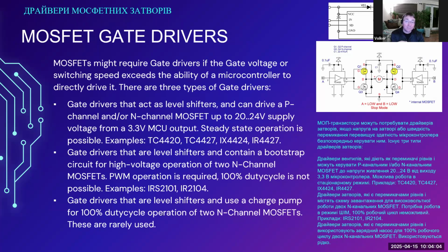Independent from this, I have mentioned switching power supplies: there are integrated chips that are basically switching power supplies using an N-channel MOSFET as the switching element, and that have a bootstrap capacitor. That's pretty much all of them. The problem with these switching power supplies is the same problem that these gate drivers have. It is essentially the same circuit.